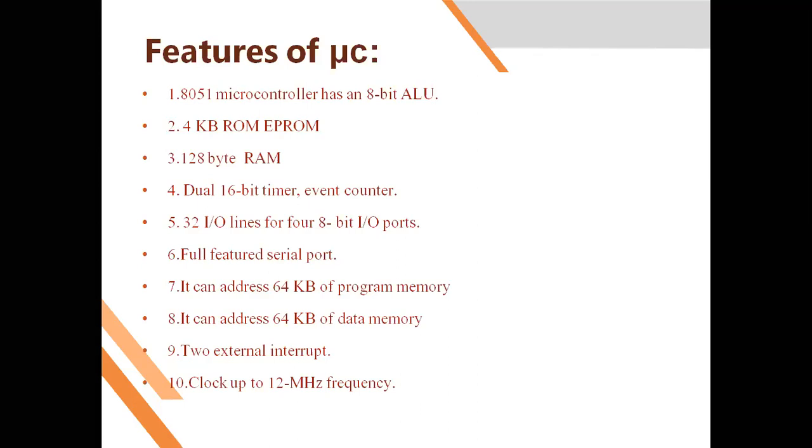So it has the capacity of 8 bit. Now for the particular application we need to go for serial transmission as well, and for that serial transmission we are having a serial port. Through that port you can transmit data serially, and through that port you can receive data serially. The upper 2 pins of port 3 are used for serial transmission.